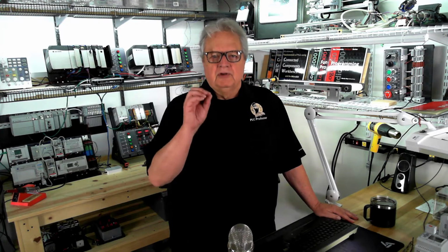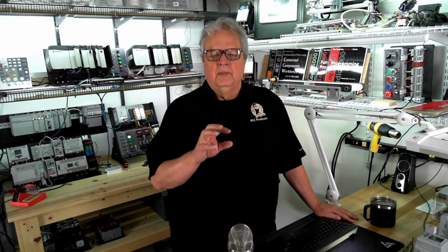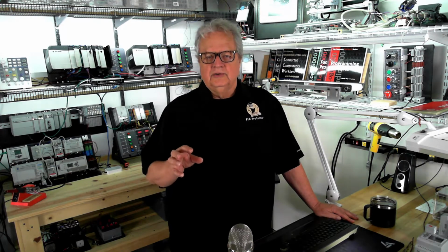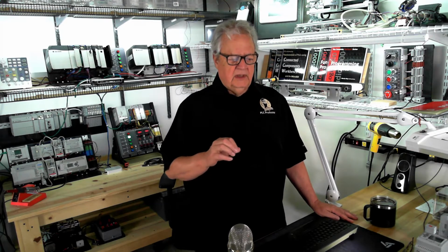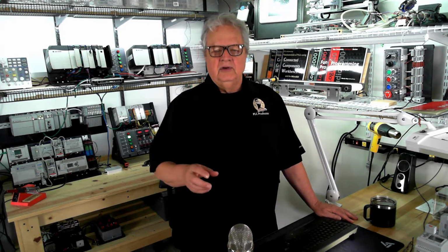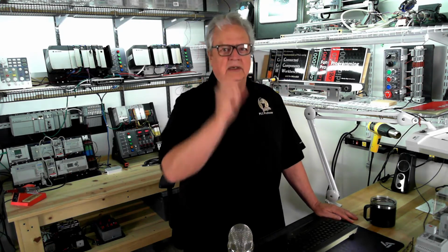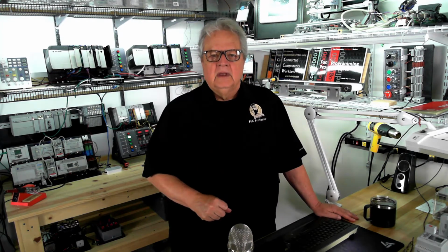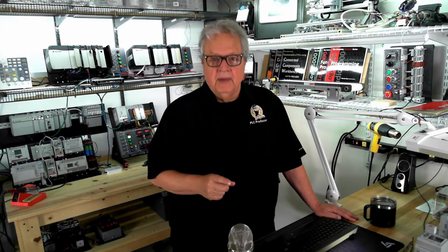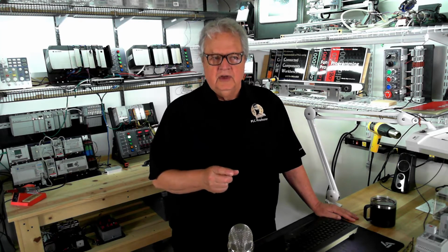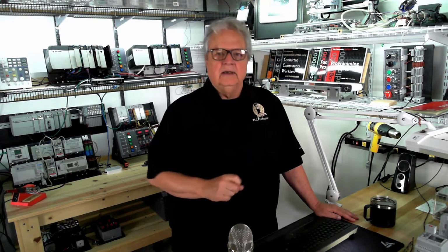But for start push buttons, we use the normally open, and for stop, we use the normally closed. So the logic that you're going to do in this lab is all built around the idea of you going and toggling a start push button, and when you do, that bit goes on and then it turns itself back off. The logic turns it off. You don't have to go in and do a second click.